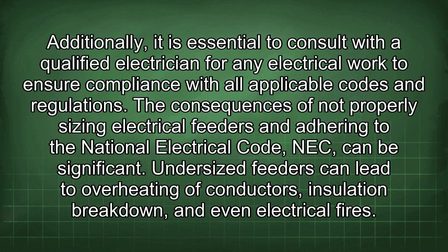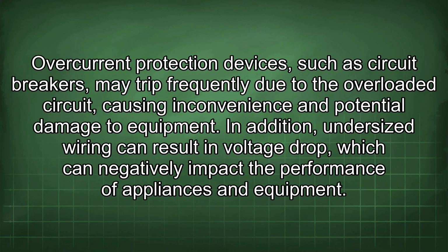The consequences of not properly sizing electrical feeders and adhering to the National Electrical Code (NEC) can be significant. Undersized feeders can lead to overheating of conductors, insulation breakdown, and even electrical fires. Overcurrent protection devices, such as circuit breakers, may trip frequently due to the overloaded circuit, causing inconvenience and potential damage to equipment.